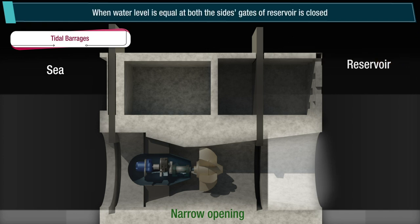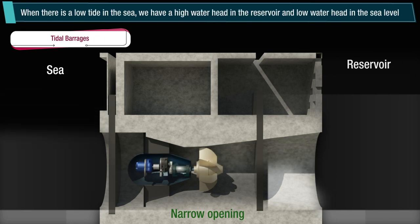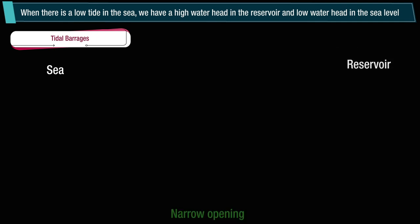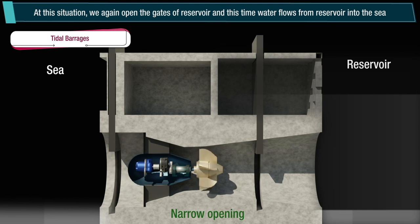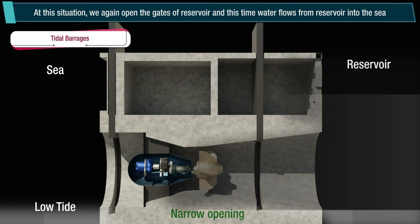When the water level is equal on both sides, the gates of the reservoir are closed. When there is a low tide in the sea, we have a high water head in the reservoir and a low water head at sea level. In this situation, we again open the gates of the reservoir, and this time water flows from the reservoir into the sea.